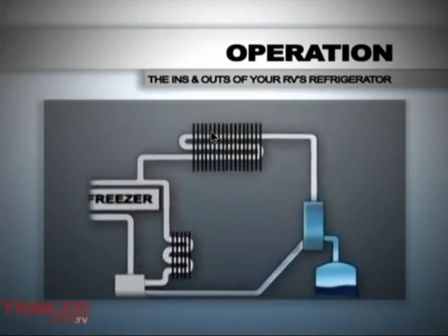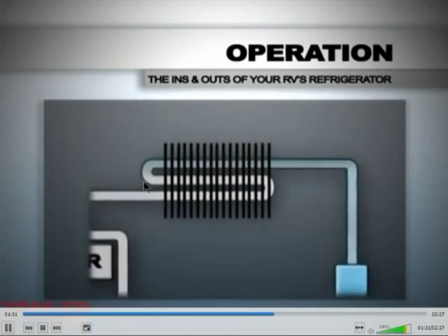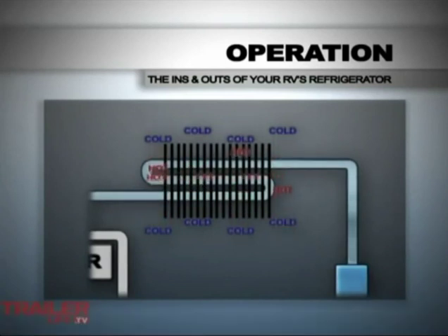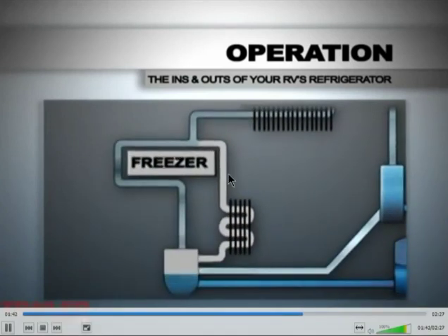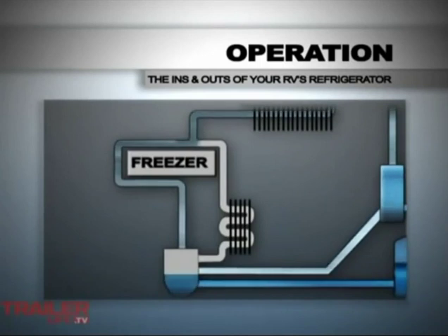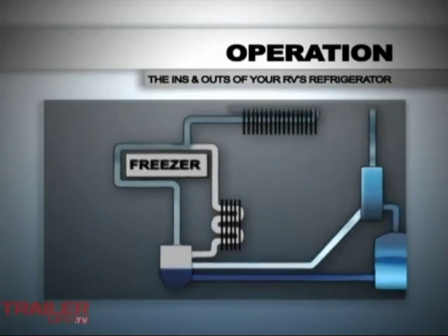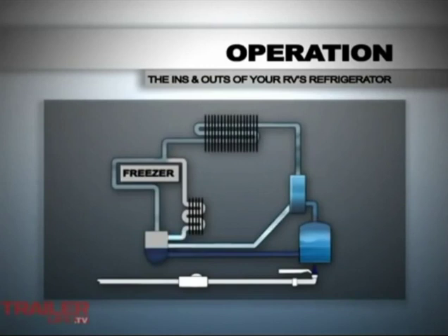Fins are provided on the tube. Here you can see that the gas will reject the heat in the condenser. Then in the evaporator, in the presence of a third gas like hydrogen, it will absorb heat at a very low pressure and get evaporated. So a 3 fluid system can also be used in the vapor absorption refrigeration system, and that gas is not reactive with the refrigerant gas. This kind of system can also be used as a part of vapor absorption refrigeration.